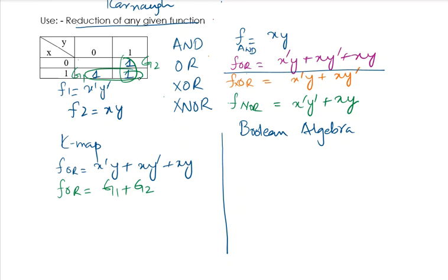Here I must mention that you should combine the ones either in pairs or multiples of pairs. So these two ones are combined together. However, we cannot combine all three of these together. Moreover, the ones are combined either in the horizontal or vertical direction, and there is no combination along the diagonal. Okay?